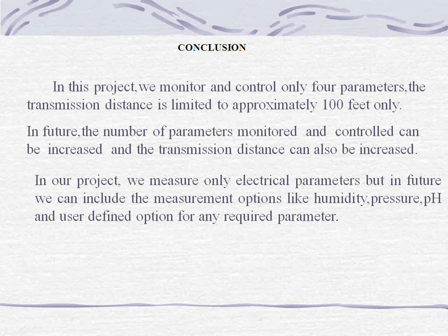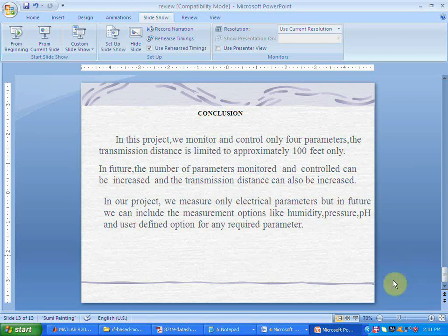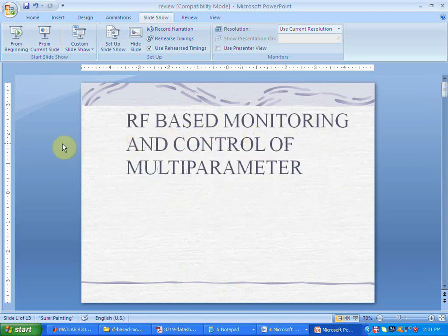Similarly, for frequency measurement, the sensing part is achieved by using a comparator. You can use a comparator based on LM741 that will find whenever there is a zero crossing: zero crossing from negative half cycle to positive half cycle, and from positive half cycle to negative half cycle.